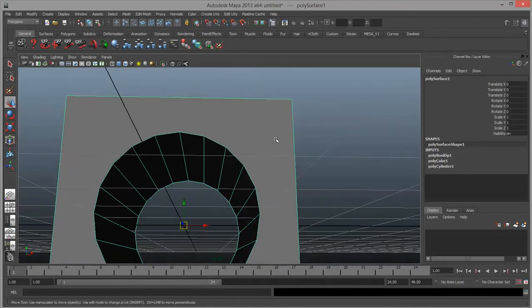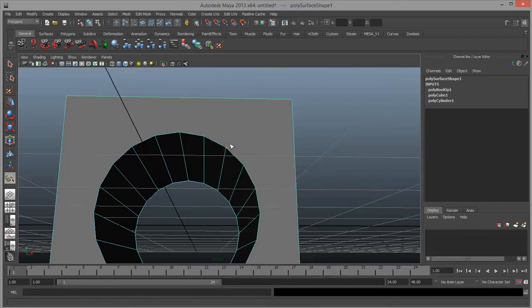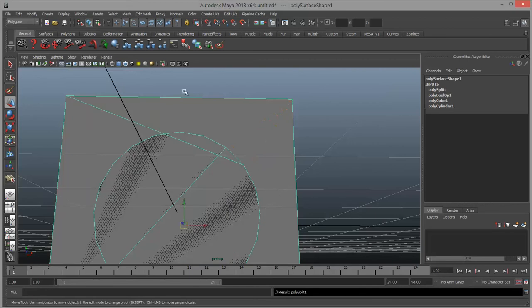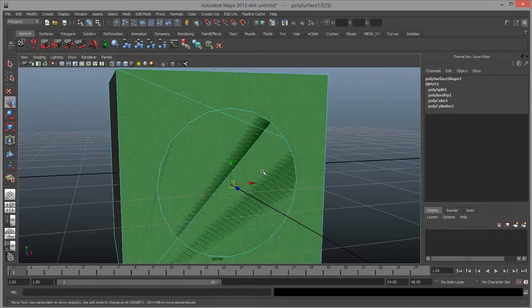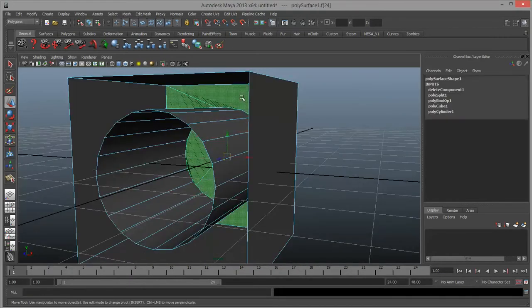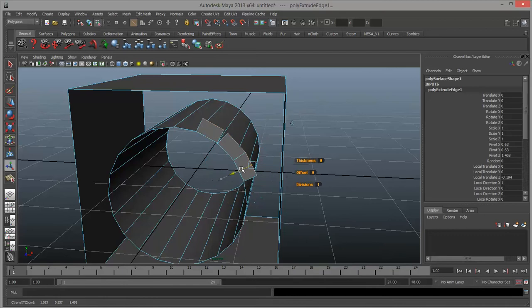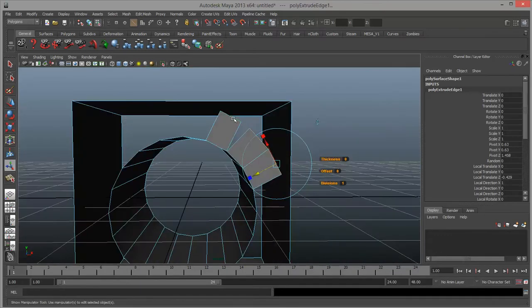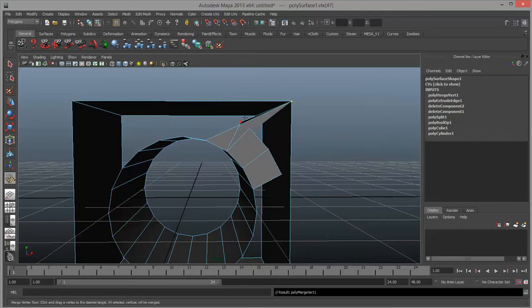And to fix these faces, what you would have to do is go through with the interactive split tool maybe, or you could extrude edges and merge those vertices and merge them to existing corners and perhaps make edge loops going through the center. You see, as soon as I do that, I get this terrible, weird looking geometry. Let me see if I can fix that there. So if I delete these faces just completely away, I can use my secondary method of grabbing some of these edges, extruding them. Let's move them out like that. And then I can just merge the vertices to that existing corner and close whatever resulting faces I get at the end. So merge vertex tool, merge, merge, merge.